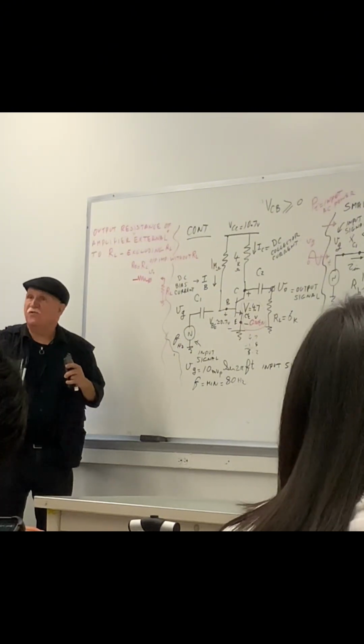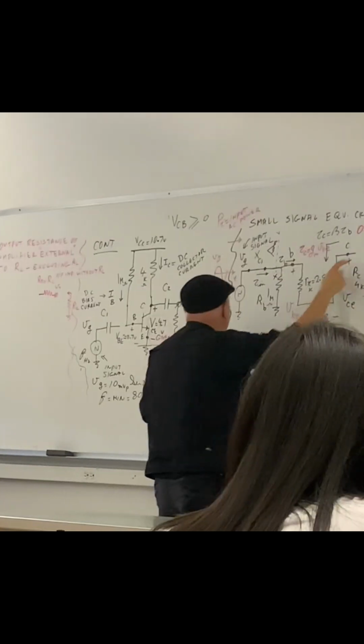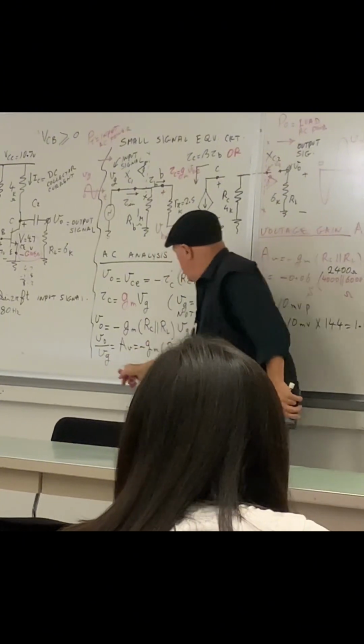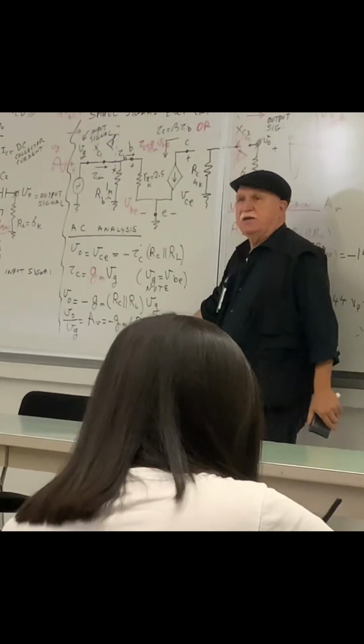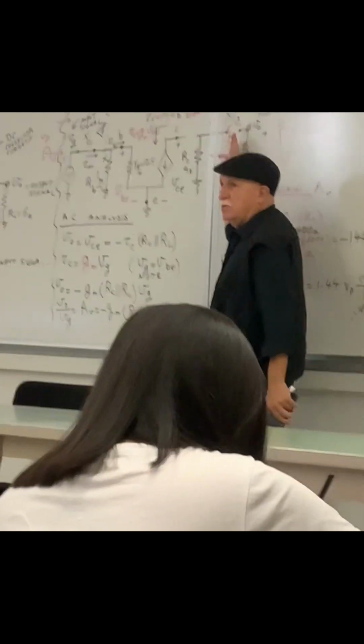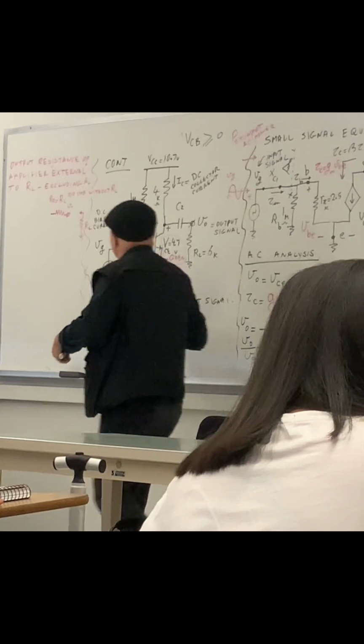But then what will be the voltage gain? How much this voltage will depend on the input. Look at this equation that I wrote about the voltage gain. What would be the voltage gain VO over VG if RL was infinity? Check here, RL infinity is not being there. It will be just the RC. So here is the answer.